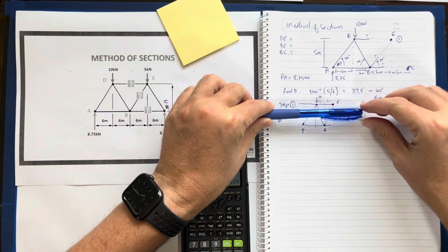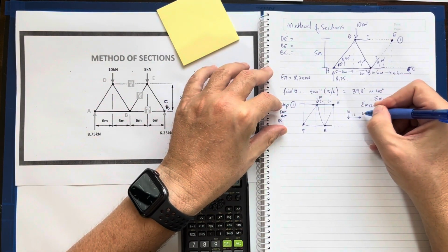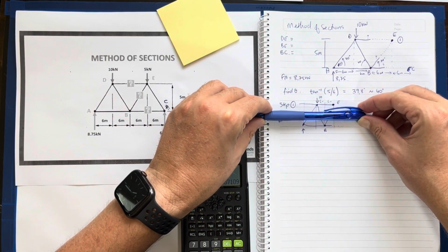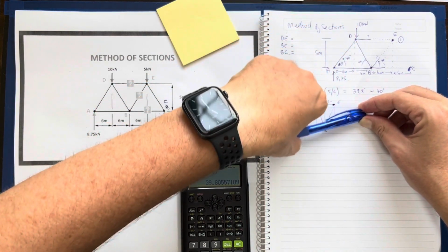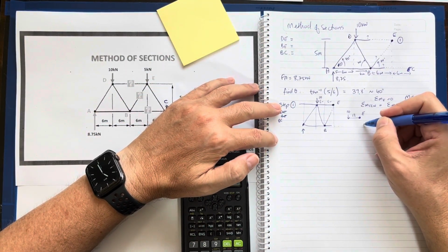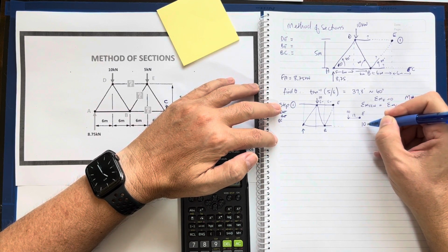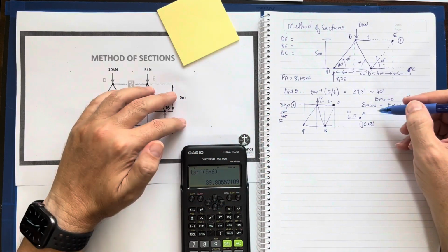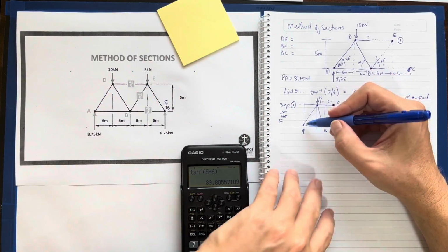That's going to make, pivoting around my point E, my external force is going to cause that little mini beam that I've set up to rotate counterclockwise. So let's go counterclockwise. That's going to be 10 times 12 meters away. Okay, I'll put them on my counterclockwise side. What's my next external force?